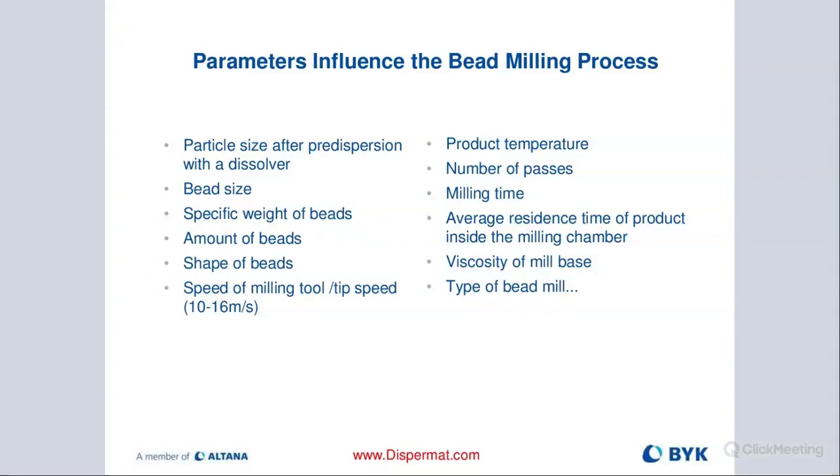Milling time, there is no real rule there. You mill until you're done, until the particle size that you desire is achieved. We have seen anywhere from 30 minutes of milling time all the way to 6 to 8 hours, depending on your formulation and how small you want to mill. Ceramic-based coatings, where you're looking for sub 100 nanometers, tend to require much longer milling times. So there we have seen different milling cycles with various bead sizes.